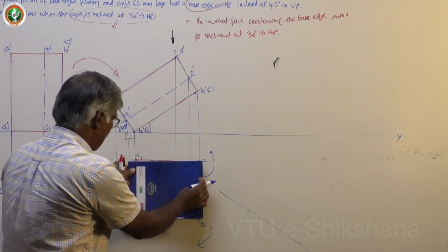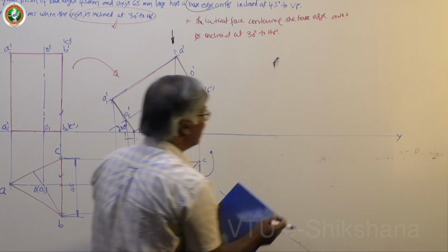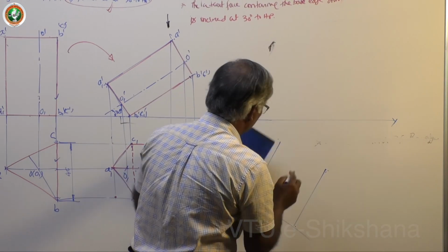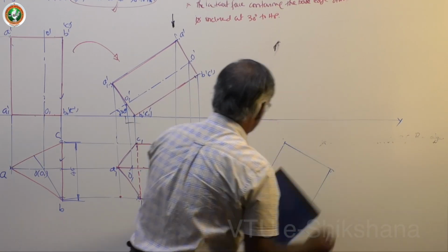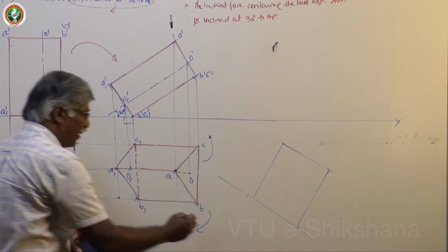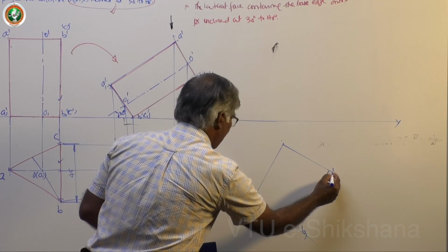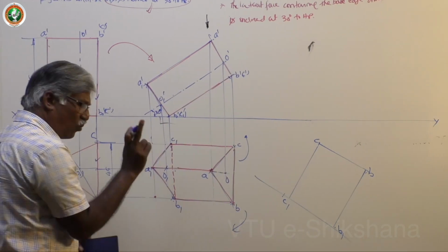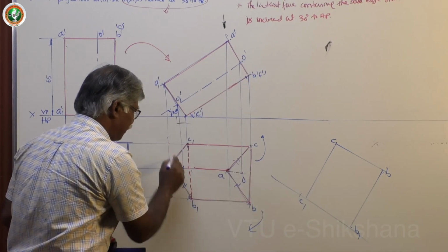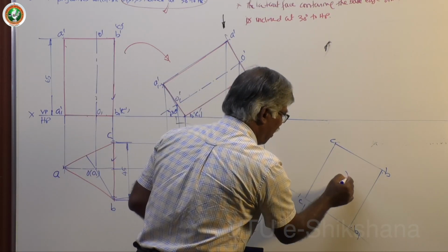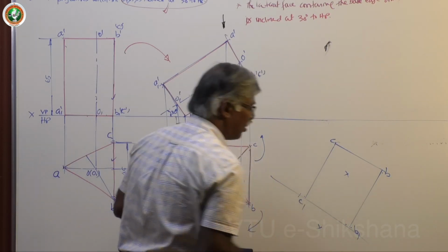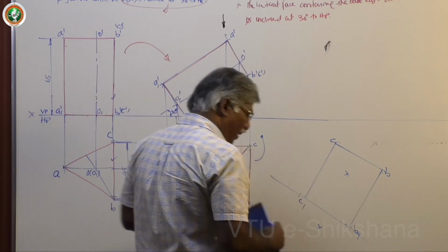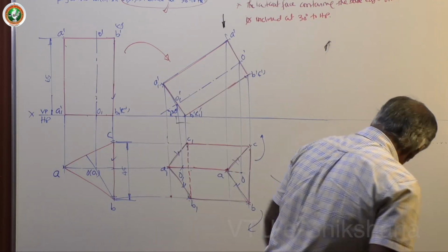Okay, now exactly same thing, about same distance is there. Using geometrical construction you complete this, that's all. Now I have completed B1 B, then C C1. Next, take only one distance, all these are equal. Okay, these two as centers, draw arc, again these two as centers, draw arc, that's all. That completes your job. Okay, now whatever is available in second figure top view, you have to repeat, that's all, nothing else.